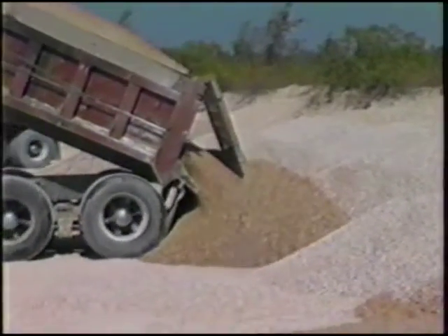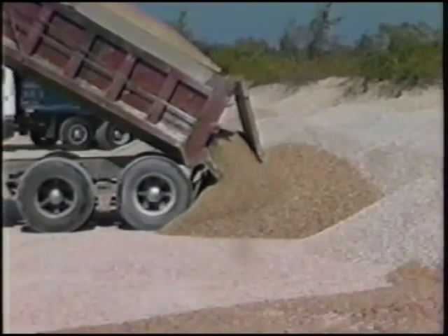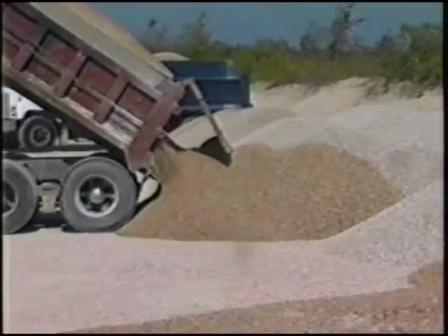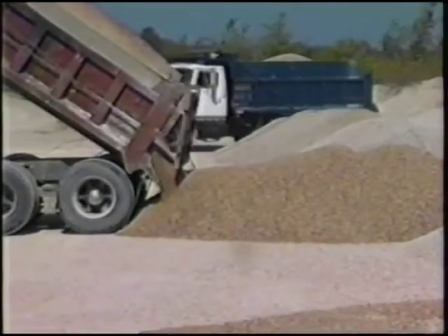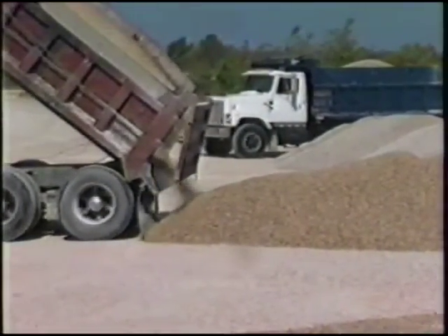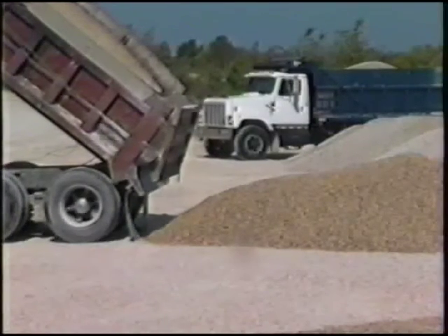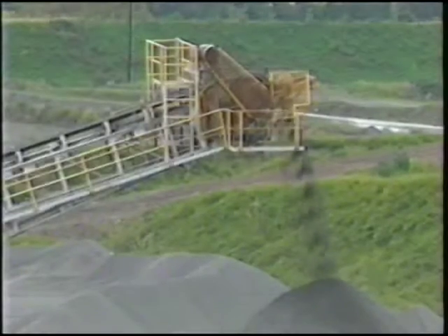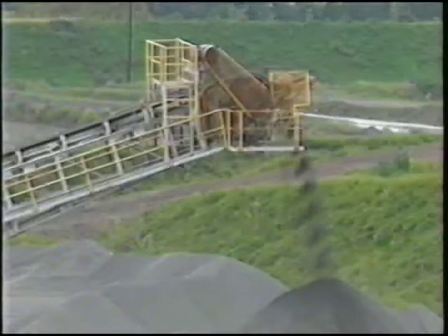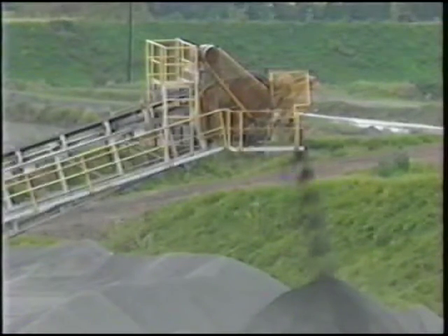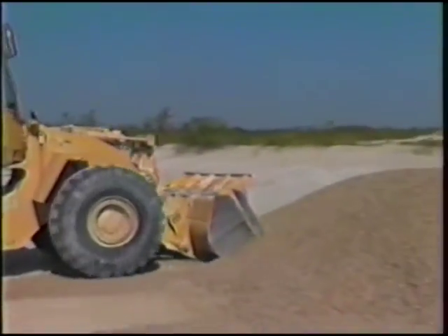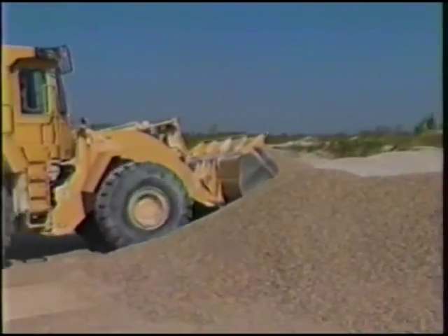No matter how the stockpile is constructed, have the material dumped and blended so that it always falls as short a distance as possible. Not following this guideline can cause segregation. When stockpiling with a conveyor stacker, it is important to make sure the material coming off the conveyor does not fall too far or down the side of the pile. Remember, the greater the fall, the greater the segregation. To minimize segregation that does occur in the fall, the pile should be blended by a loader.